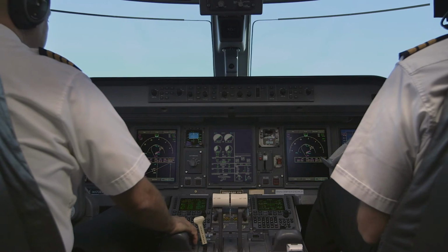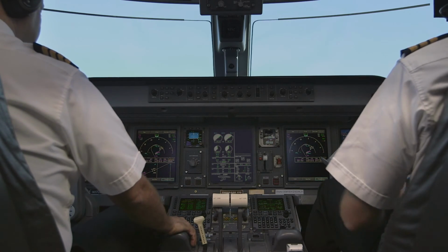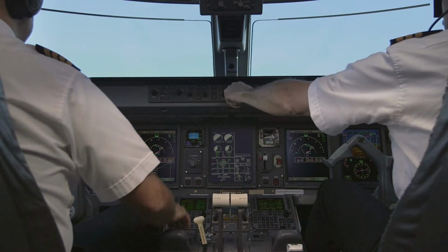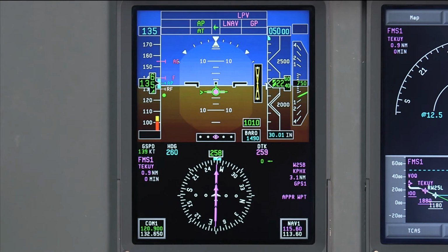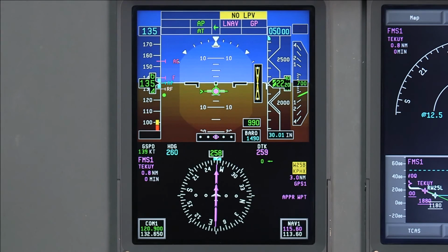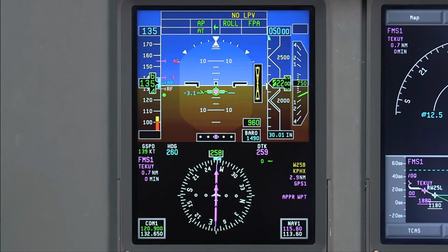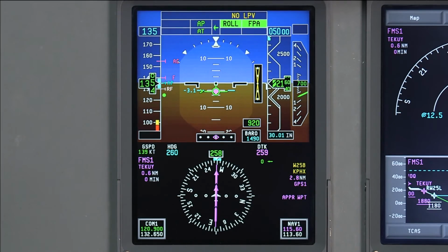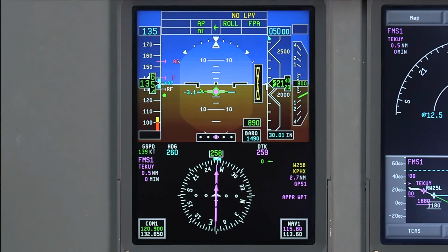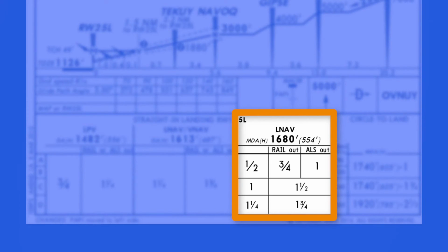Pilots must be familiar with the fail-down capabilities of their SBAS system. An amber X over the vertical path indicator, along with an amber LPV annunciator and amber approach ID, are displayed on the PFD when conditions exist that would prohibit descending to LPV minimums. The flight crew may have the ability to continue the approach to LNAV-only minimums if an amber LPV annunciator is displayed.